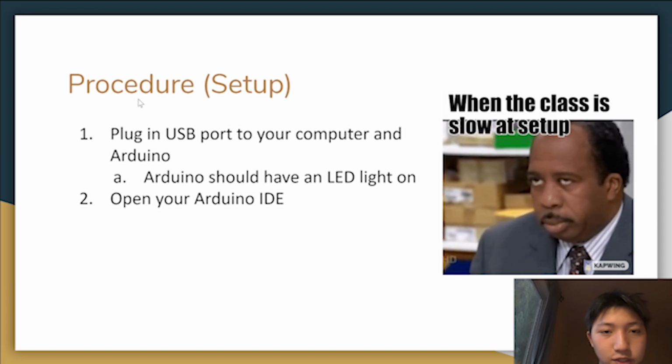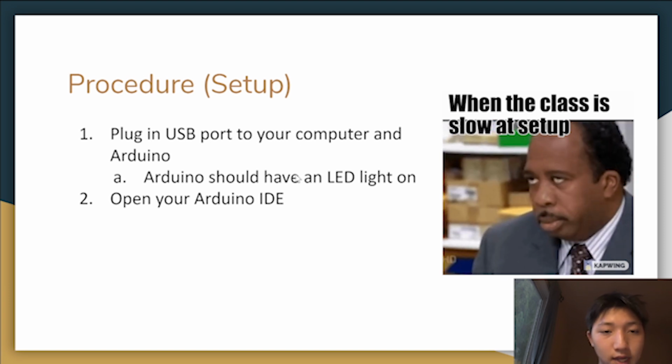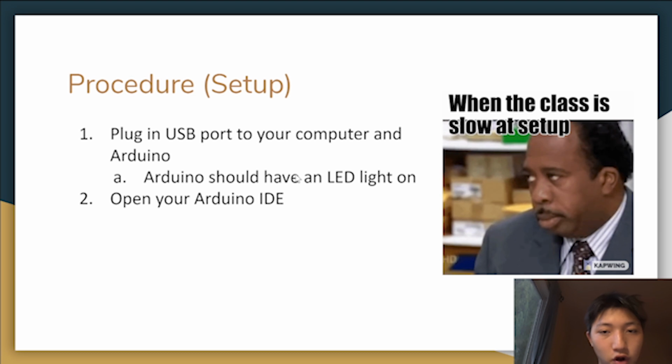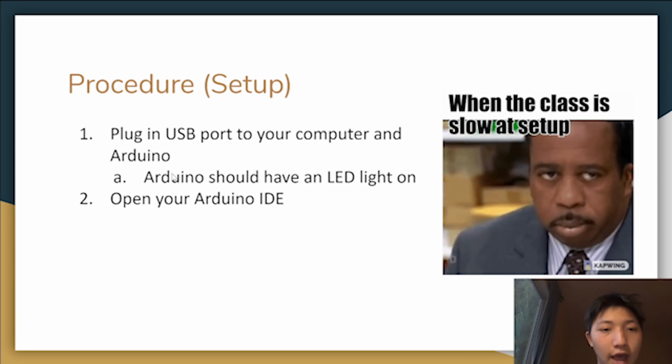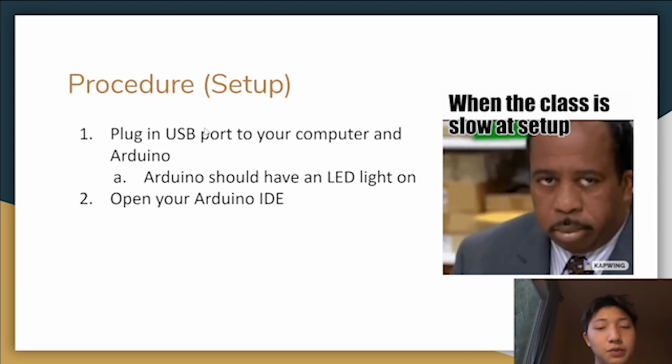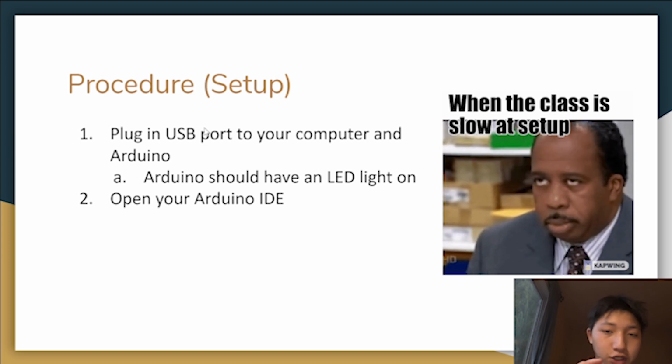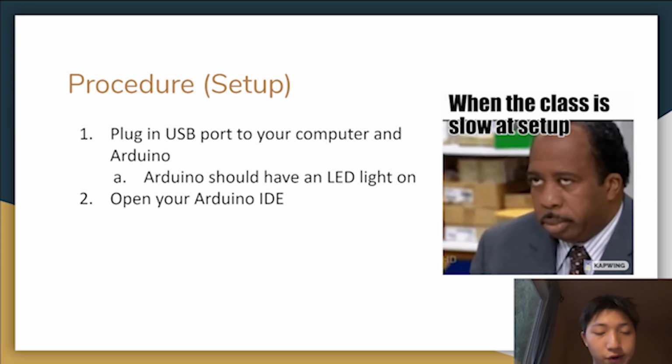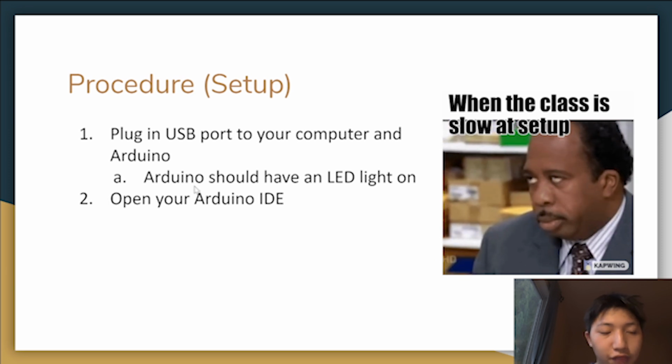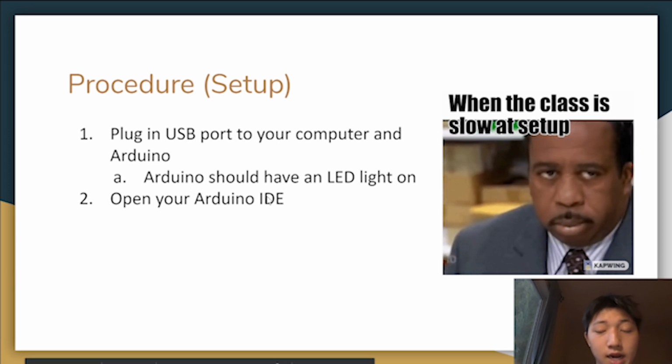So for the procedure setup, you want to first plug in your USB port to your computer and Arduino. And once this happens, an LED should be blinking, and that shows that the Arduino is ready to go. And then you should open your Arduino IDE.